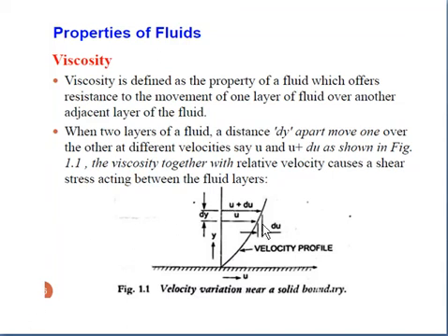See what happens: the velocity of this first layer is less and the velocity of the adjacent layer above is more. Why does this happen? See, this is the velocity profile. This is the bottom, or a datum. Suppose this is a river flowing in this direction, and this is the bottom layer, the datum of the river, the base of the river. When the water is flowing, at this part there is no movement of the water. As there is no movement, there is no velocity. Here you can see zero velocity at this bottommost point.